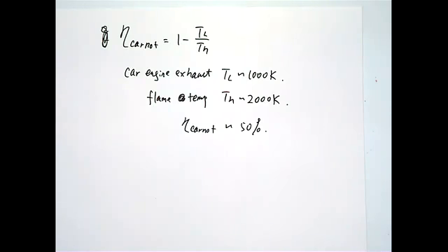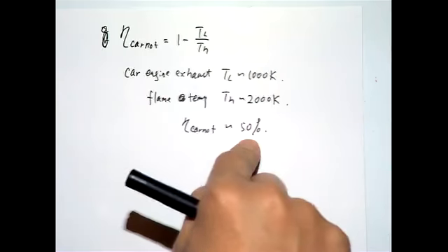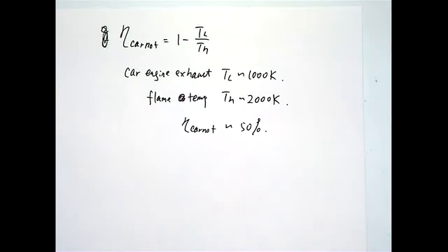Diesel engine is more efficient. Diesel engine is on average about 30% more efficient than the petrol engine. 30%, I mean in relative terms. In absolute terms, diesel engine is about 30 to 40% in terms of thermal efficiency, so relative to petrol engine it is about 30% more efficient. But for both engines, they are still pretty far away from the theoretical limit.